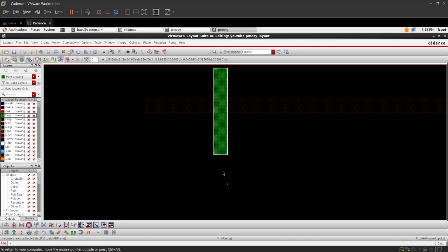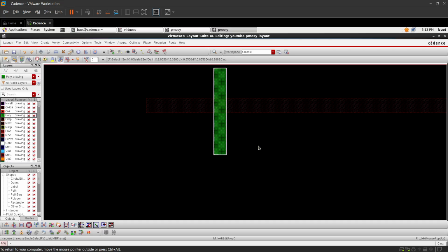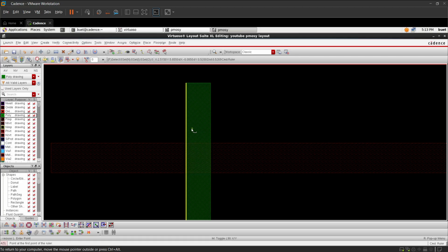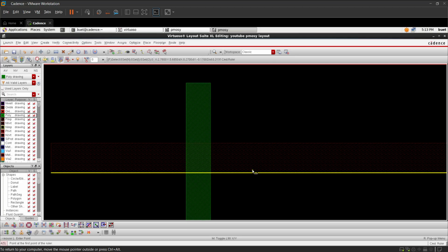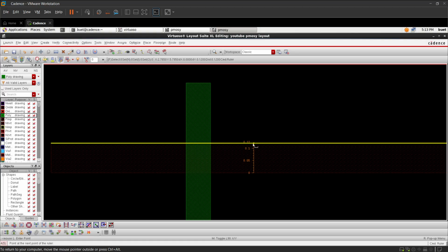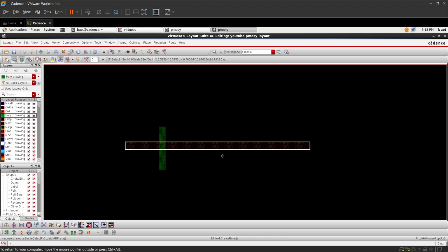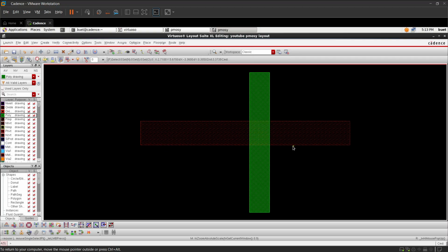Press apply. Okay. Sorry, I have done its width. It should be width. It should be 0.1. Just apply and okay. So right now you got your poly layer and oxide layer. It is 0.1 and this is 0.12. It means we have satisfied our parameter. Select this, just drop this, chop and fit. It is done right now.